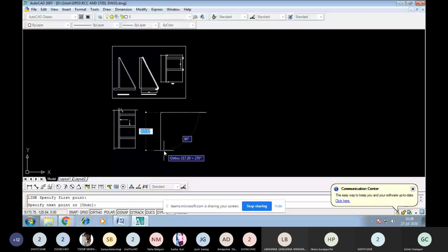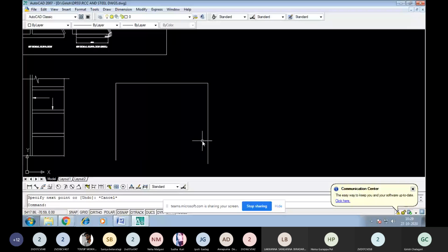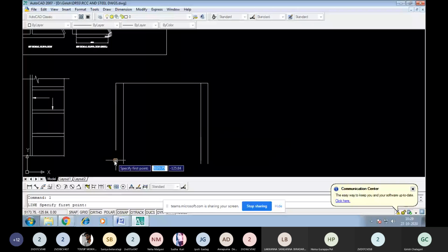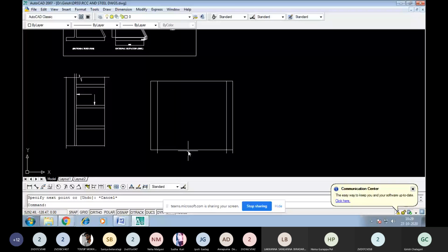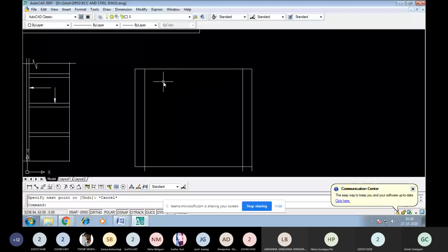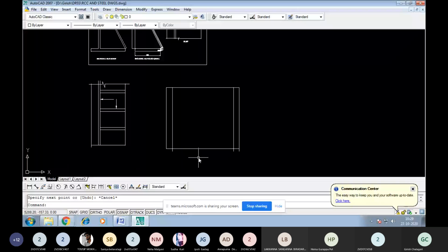And the counterforts are provided at some regular intervals. This is one counterfort, this is the other counterfort. At the bottom it will stop here, and at this level we have the heel slab. So this is the height of the counterfort, meaning the stem. These are two counterforts, and in between I am taking this section. What happens? The entire area is fixed with counterforts on either side. The bottom is fixed with the heel slab. So only one end is free.